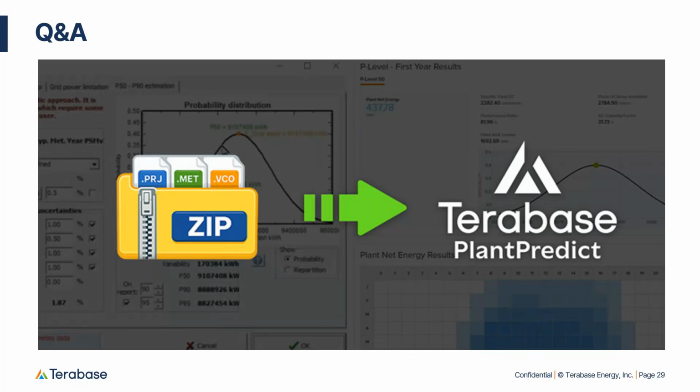I think you covered that, but it was maybe a lot. Yeah, it's really a question of difference of philosophy and what you're trying to achieve with these. There is no way that is better than the other. The advantage of the PVsyst approach is that you don't have to know anything about this organization to be able to compare all your losses. But the advantage of the PlantPredict approach is that you can actually compare, in absolute value, two different losses.